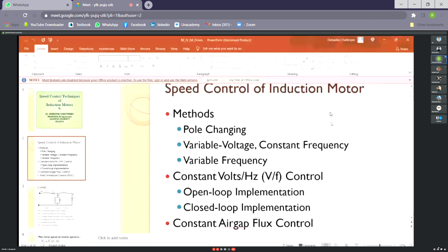As you have read in your earlier classes on induction machines, the rotor magnetic field speed with respect to the stator stationary axis is also omega s, the synchronous speed, and the speed of the stator magnetic field with respect to the stationary axis is also synchronous speed. If there is a speed difference, there won't be any steady torque produced. There can be instantaneous torque, but the average torque will be zero.